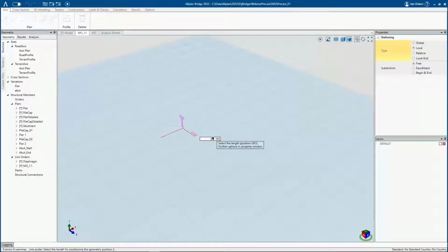First step, what I need to do, as I explained before, is create a virtual axis. This is the template length of the element. In this case, I will type in 10 meters, but this value doesn't matter later because we will determine the end geometry by defining this element between two 3D points. So let's type in just 10 meters.